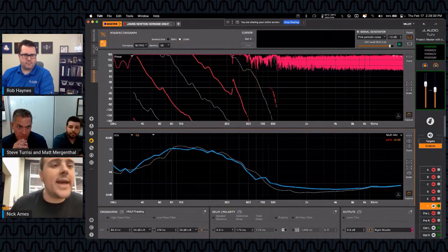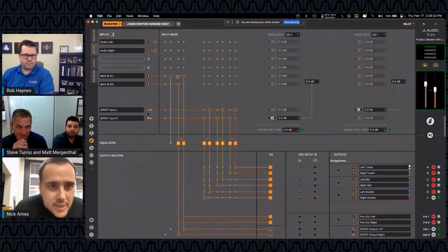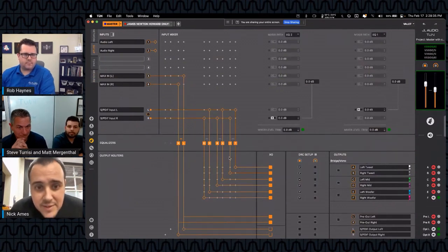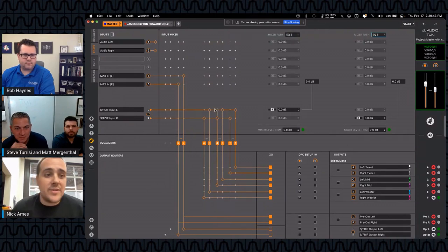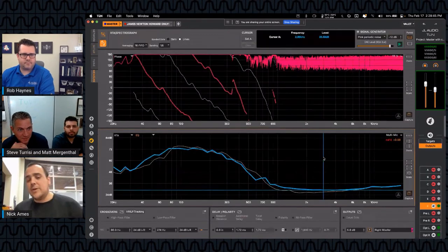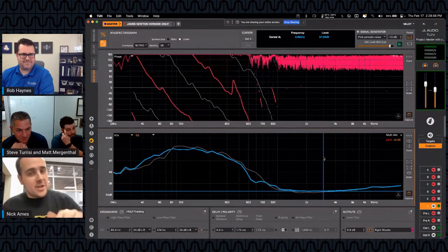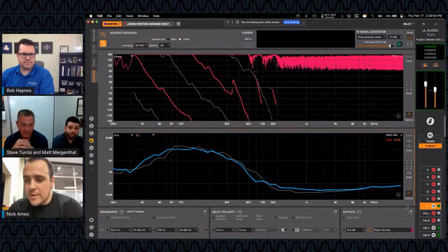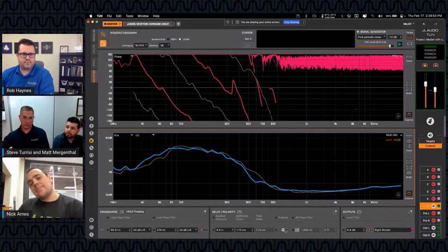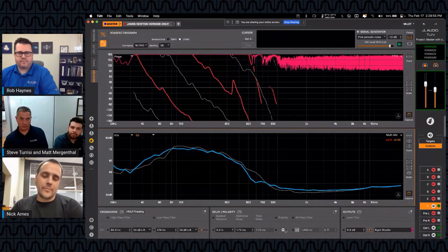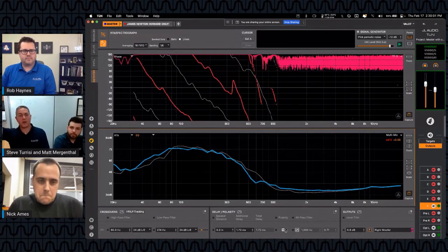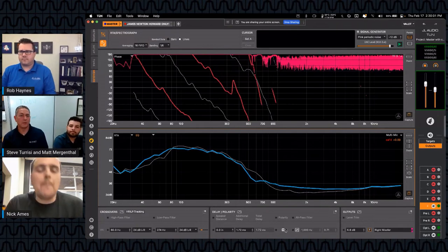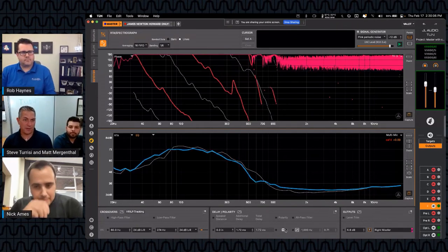Yeah. Or wait, hang on. Actually, technically, it could also be that in the input mixer, one of these is flipped. No, they're not. Okay. The input signals aren't flipped. So, all right, never mind. I just wanted to say it, because there is one other possibility, right? There's another place where polarity can get inverted. And this kind of goes back to, we're looking at everything between where the signal started at the signal generator on max and going through every piece of electronics, including the software, before going through the driver and out to the microphone. Yep. Indulge me. Flip that polarity, please.